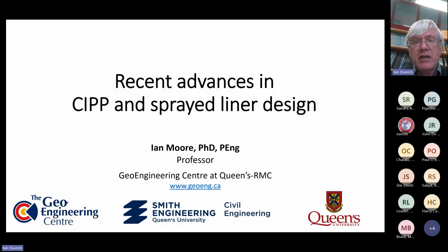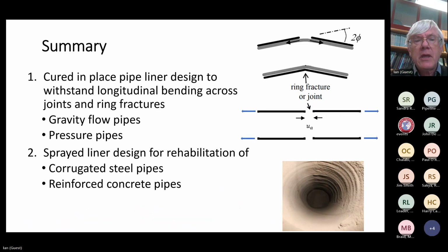And yes, I'm going to be talking a little bit about some work I've done on cured in place pipe liners and sprayed liner design. So on the cured in place pipe liners, one of the things that we need to think about for some liner projects is the impact of ground deformations on the performance of those liners.